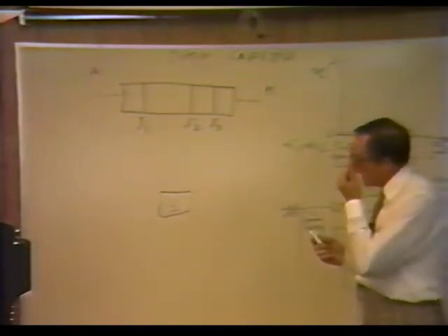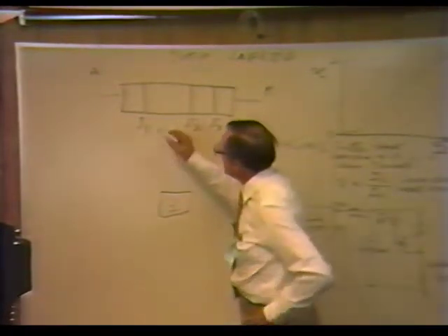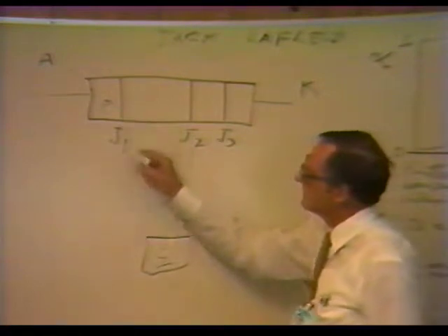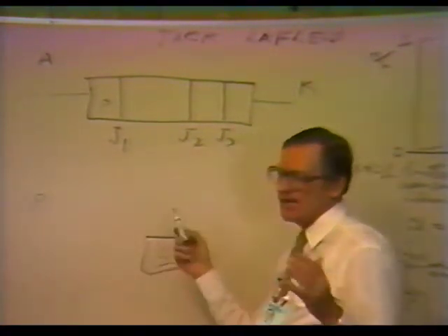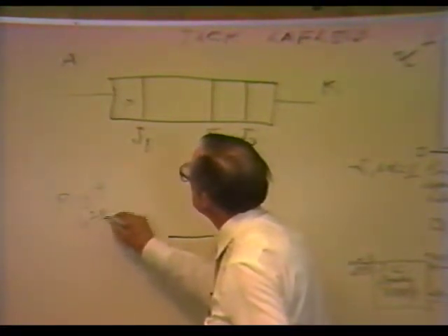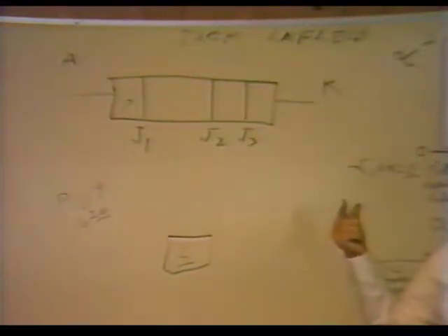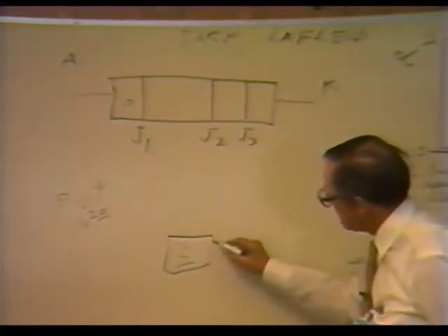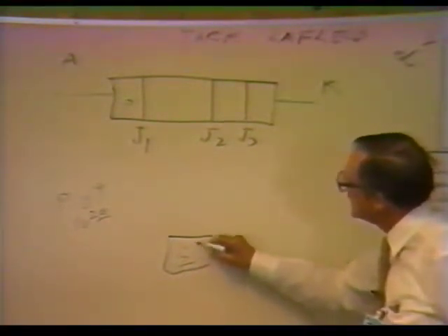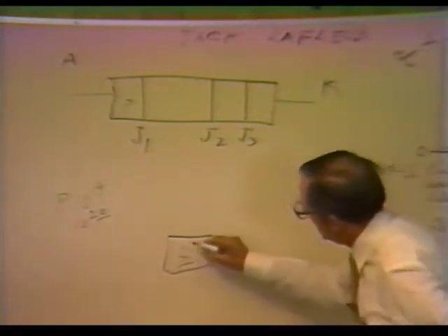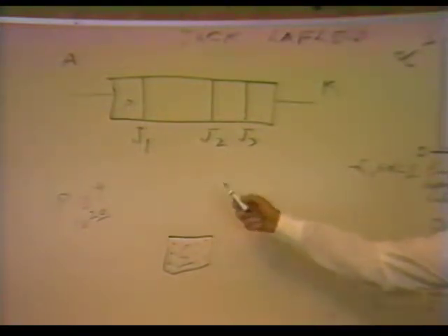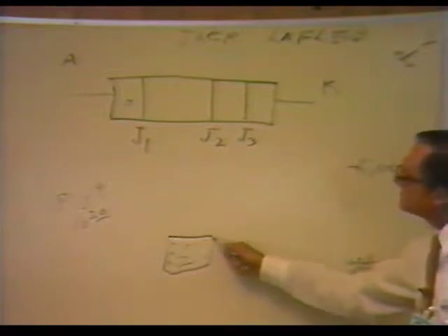And to give you an idea where we are, in this P layer, which we call the anode, we will dope in for an SCR somewhere around 10 to the 19, 10 to the 20 impurities per cubic centimeter. Now, what does that mean? That means we have in the atomic structure, we're putting atoms of, in the case of a P device, boron atoms, and we're putting them in there.